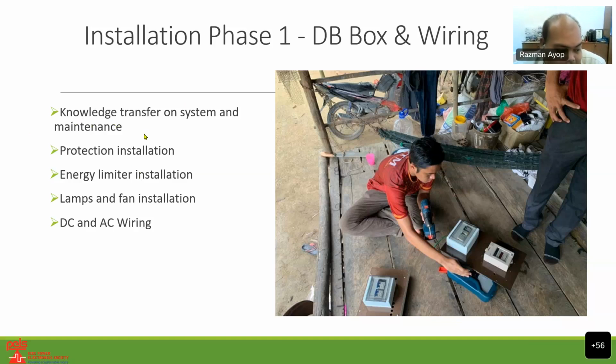Basically, you just ask them to clean the PV every 3 months and not put anything on the PV. As you know, PV is actually quite hot. Even if the temperature is only 20 degrees, the PV is around 45 degrees Celsius. If the temperature is higher, the PV temperature is much higher than the ambient temperature. So if they don't know, they might put some clothes there to dry them quickly. That becomes a problem.